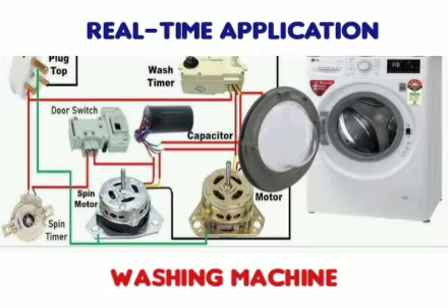For example, if you are setting a total of 30 minutes, 10 minutes is allotted for rinsing, 10 minutes for soaking and 10 minutes for drying. It will split the time according to the work you have given and reduce the time whenever the work gets completed, until it reaches 0. The counter will count how much time is taken or how many times the clock has been initiated for controlling that particular operation or application you have given. So this is the real-time application of timers and counters.